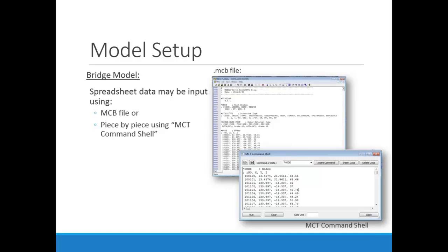I also find I'll use MCT command shell where the geometry will update and I know nothing else changes. So all I need to really update is my node locations. So I just paste that in, run it, and everything carries forward. So these are very useful tools.